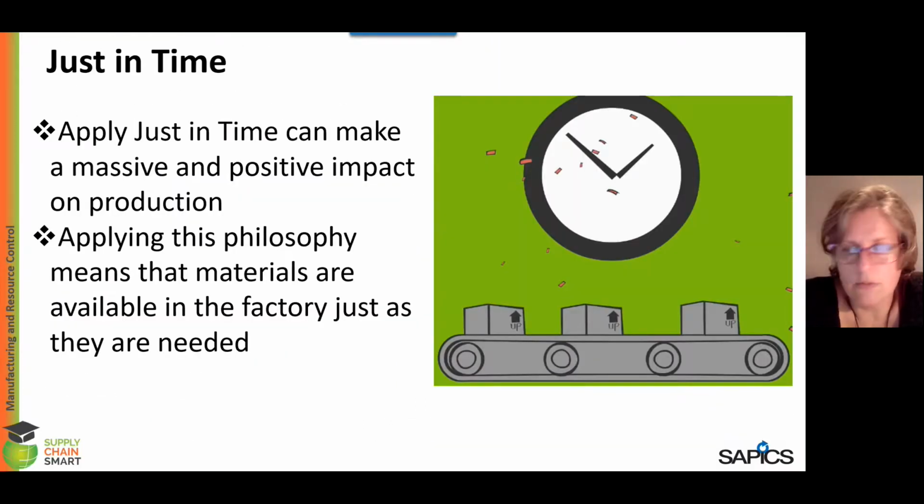Just in time is a critical process that is looked after, making sure that you have the right stock just in time. From a just in time perspective, what you're trying to achieve here is minimum inventory in your process. So for example, within the Toyota industry, if I need to have a harness to go into a vehicle, which is all the electric wiring, I would send a job card in the morning to the supplier and say, I need 4 harnesses for 4 vehicles. The harness manufacturer will then make and assemble in that 4-hour period 4 harnesses for 4 vehicles, which will then be delivered to Toyota to go into the vehicle.